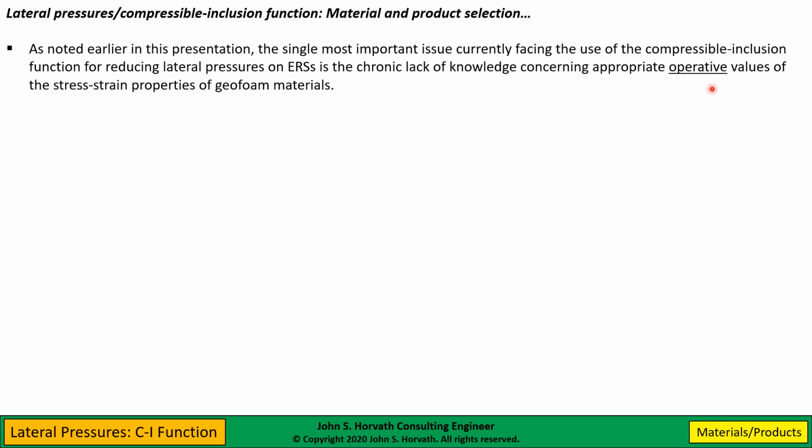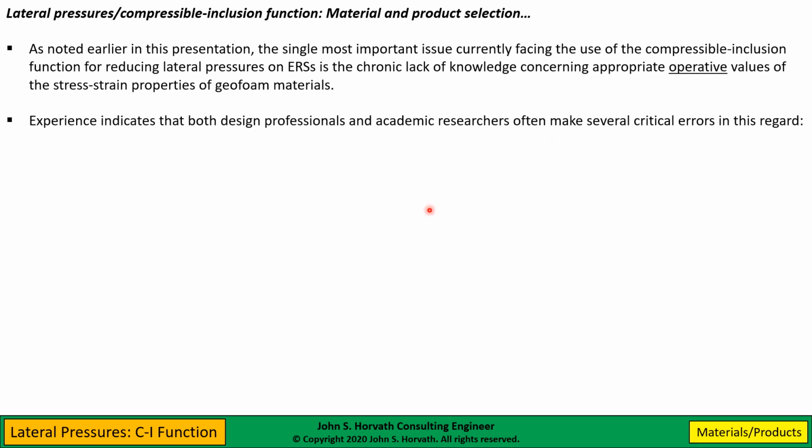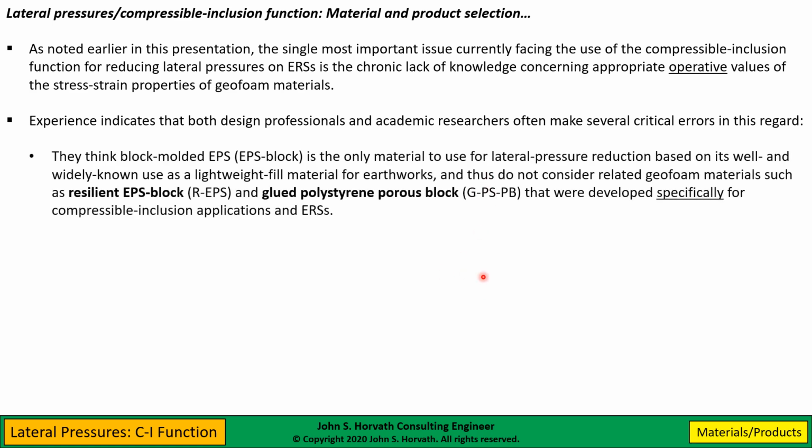the chronic lack of knowledge concerning operative, keyword here is operative, values of the stress strain properties of the geofoam materials. And my experience is that both design professionals and academic researchers make some critical errors in this regard. Number one, they think that block molded EPS block is the only game in town to use for lateral pressure reduction, even for a compressible inclusion,